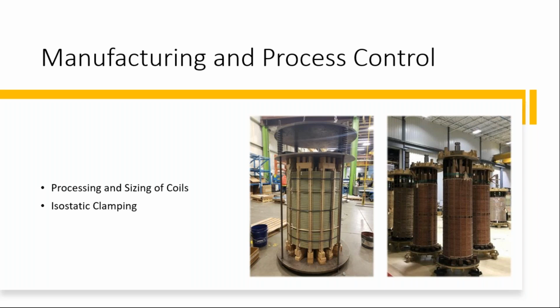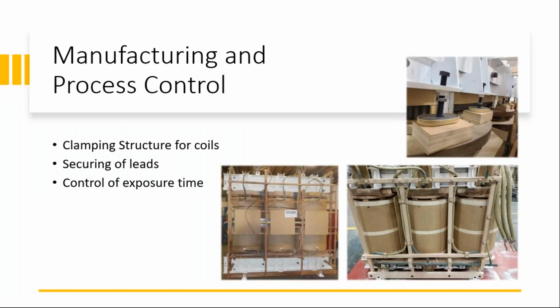So these are a few things which are taken care of in the winding process, and also as we prepare the phase before we land onto the core. When the phase assembly is completed, the coil is landed onto the core, the connections are completed, and it goes into vapor phase drying or the conventional drying process.